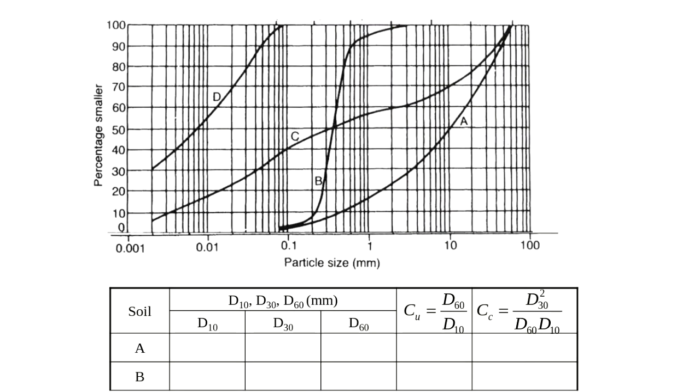Okay, this is a different thing. Again, this is something that you'll be tested on in the laboratory quiz tomorrow. It's a part of the classification procedure, something you will do again for your online quiz in week 6. So you need to get these coefficients. The thing you should remember is that we get these coefficients only for coarse-grained soil which is non-plastic. If there is no plasticity, in this case we use these coefficients.